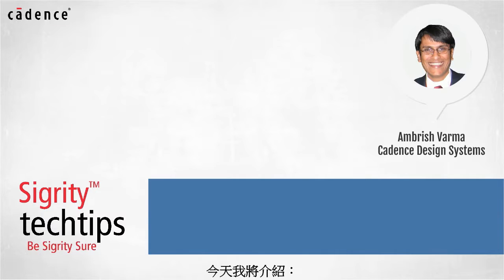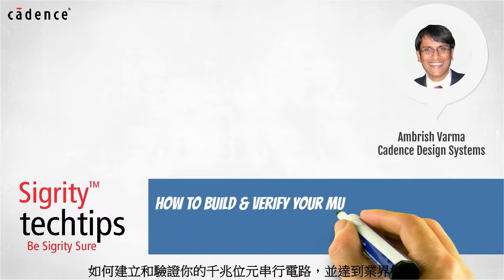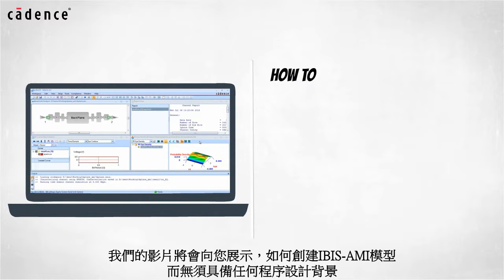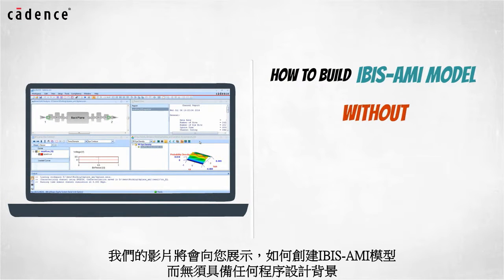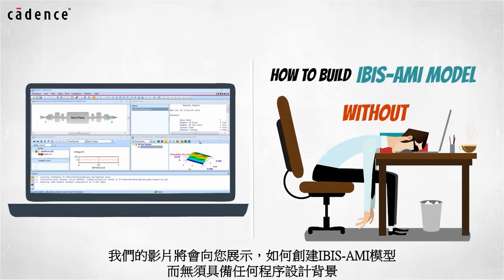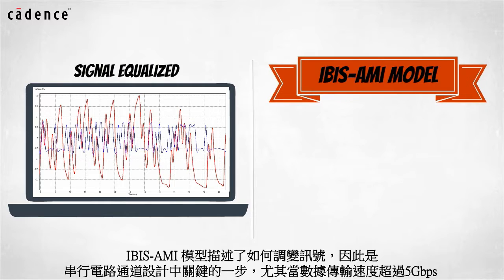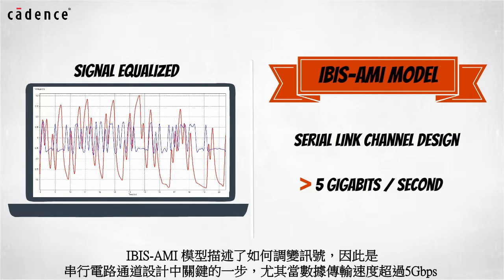Today we bring you another installment of how to build and verify your multi-gigabit serial link to meet industry compliance standards. Our video today will show you how to build an IBIS-AMI model without having to become a programmer. Since IBIS-AMI models describe how the signal is equalized, they are a critical part of the serial link channel design when data transfer speeds exceed 5 gigabits per second.